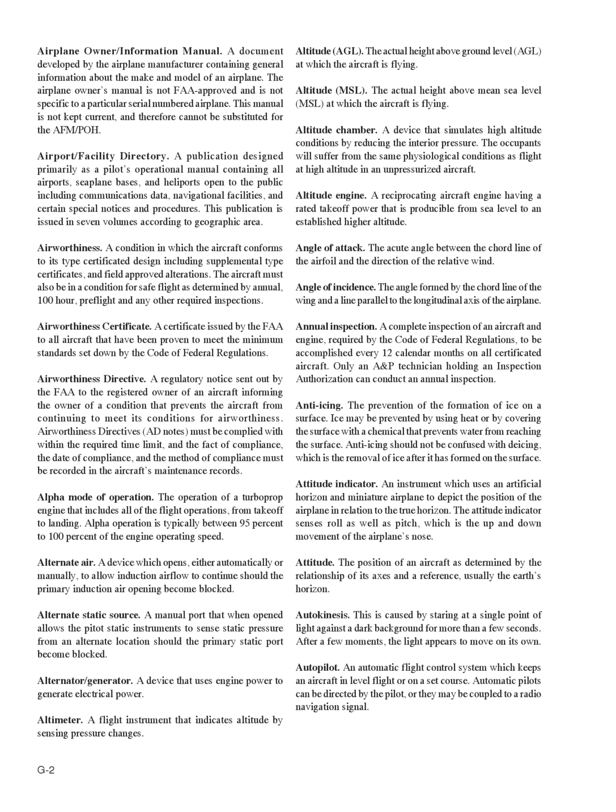Altitude engine. A reciprocating aircraft engine having a rated takeoff power that is producible from sea level to an established higher altitude. Angle of attack. The acute angle between the chord line of the airfoil and the direction of the relative wind. Angle of incidence. The angle formed by the chord line of the wing and a line parallel to the longitudinal axis of the airplane.